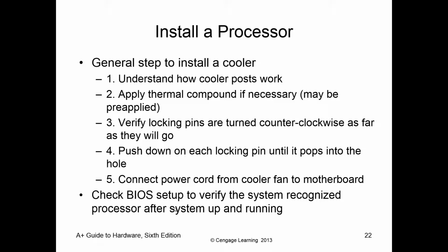Once you've applied it, you will verify that the posts for the cooler are connecting to the motherboard, and you'll be locking them. You'll be locking them by pushing down at each of the locking pins until it either pops or it locks into place. Once you make sure and verify that the cooler is properly seated, you want to plug it into power. That way, well, it has power. Also, you'll check the BIOS to verify the system recognizes the processor and the fan.